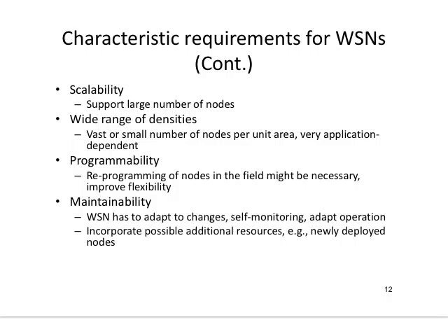Your system has to be scalable in such a way that allows the number of nodes in the system to grow very large, yet they can use the spectrum or the capacity of the system efficiently, using, for example, interference mitigation. So if the nodes are close to each other, we have to divide the capacity. But if they are not in the same interference range, they use the same capacity of the system. So we need to divide the resources intelligently to support this scalability.